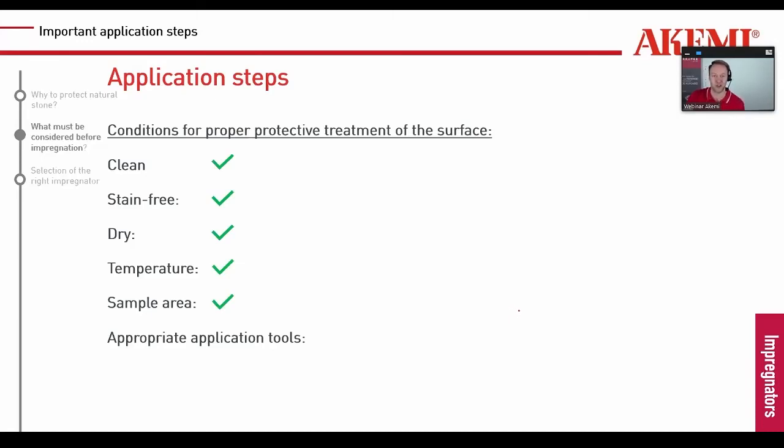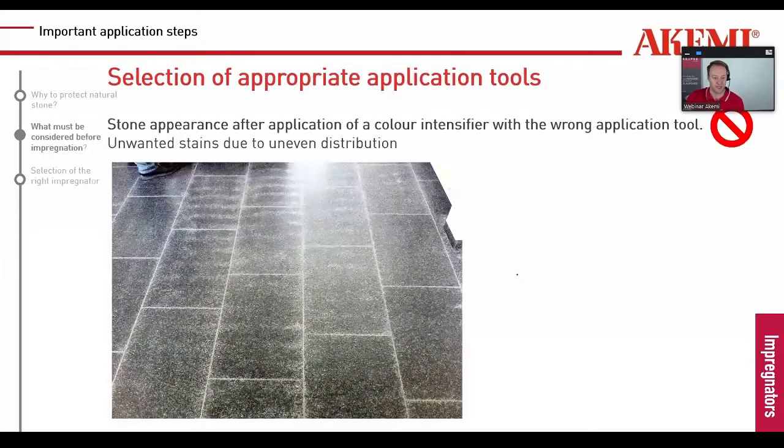You see here, there was a color intensifier applied on the stone, probably by a paint roller or something like this. And you can see directly where the roller was full of material and where it was not. So this is not a good result. Of course the client will not be happy and will not pay for that. So we don't recommend rollers.